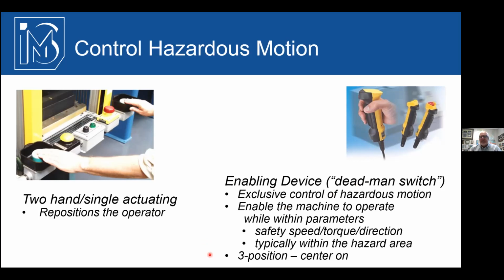And for the newer ones today, if you have some that are still two position, consider going to a 3-position switch where the center is on. The reason for that change to the standard and the recommendation for the center on position is that in some cases, when somebody was injured, instead of them dropping or opening, typically you squeeze this thing in.